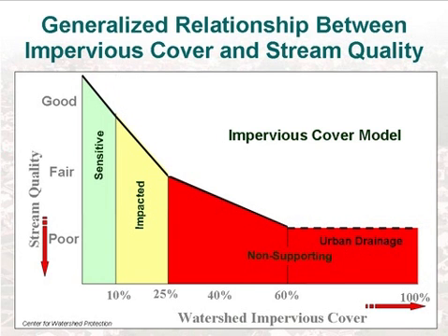So it's a management tool. Absolutely. And again, lots of factors could cause this relationship to vary somewhat. For instance, the placement of that impervious surface within the watershed. If it's evenly distributed or if it's concentrated in one place, may make some differences. Another thing to point out, too, is that, as I said before, EPA is focused mostly on chemical parameters. And if you look at some of EPA's reports on stream quality, you won't see much in the way of an assessment of physical or biological impacts, and yet we know that they're happening through studies like this. So we need to look broadly at lots of different information to figure that out.